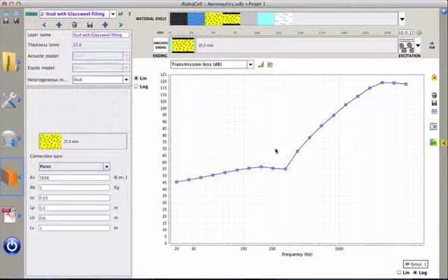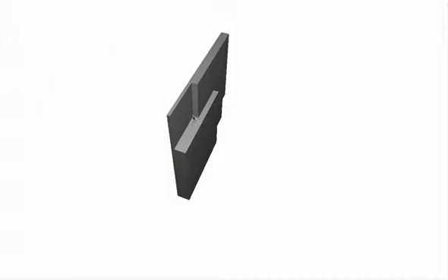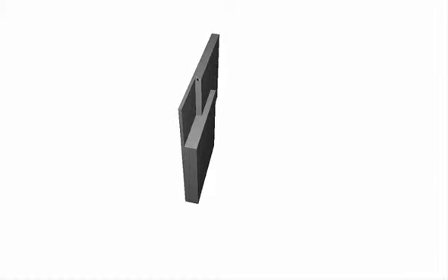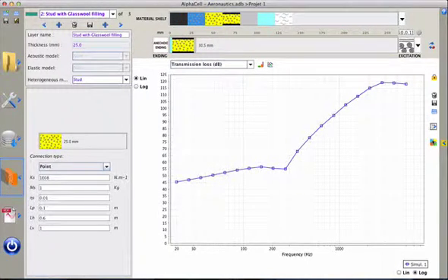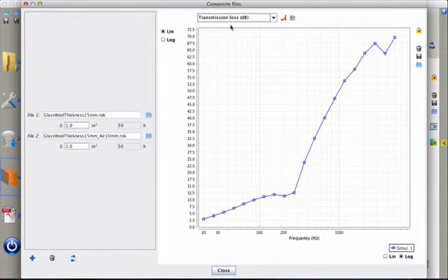We can compute an approximation of the sound transmission or sound absorption coefficient with the transfer matrix method. So for example, here we have a material or a system, so a set of layers with different thicknesses on one plane, and we can have an estimation of the sound transmission loss or the sound absorption coefficient by using a composite tool, which is here on AlphaCell. We load the information about the sound transmission or sound absorption for each thickness of the layers we have, and the surface information.